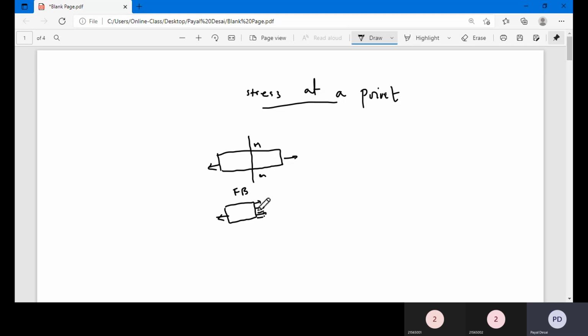Okay, and of course, what is the resultant of these smaller distributed forces acting over the cross section? The resultant will of course be, because the body has to be under equilibrium, sigma times cross sectional area, and this is how we define it, because the resultant of these smaller distributions should be equivalent to the external force. From this equilibrium equation only, this is a very simple case where we write the equilibrium equation and get the resultant, but this is how we define the intensity of these smaller distributions of the forces, we call it stress, that is force upon area.